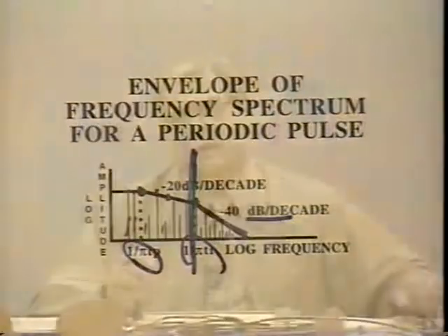Well, if you had two equal level digital signals, and you were worried about one cross-coupling over to the other, say they're both 3.3 volt digital signals. By the time you get above that second corner frequency I've identified there, you will not have enough energy from any one of those frequencies that if it couples over to the other signal, it'll be enough to shift the logic level. So for equal amplitude type signals, that second corner frequency pretty much indicates the limit of the upper frequencies we've got to worry about.